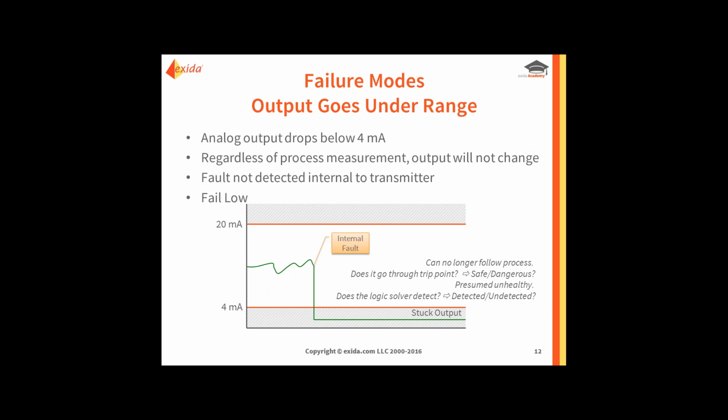And it's the same story as for those fail high failures or overrange failures. We don't really know if this is a safe or dangerous failure. We don't really know if the logic solver will detect this. So that's why we classify them as fail low.